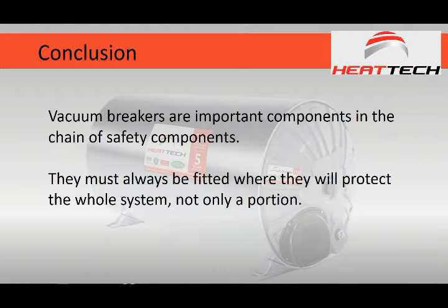And other than that, Henry, have you ever actually heard about the standard 10254, where it says it has to be above 150 millimeter on your highest point? So this is the first time you've been made aware of it. And because most of the plumbers are not aware of it, they don't do the installation like that.